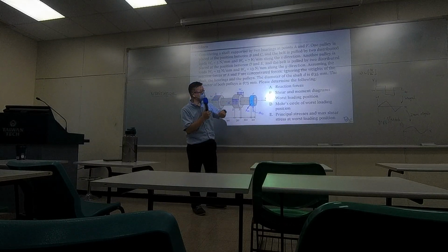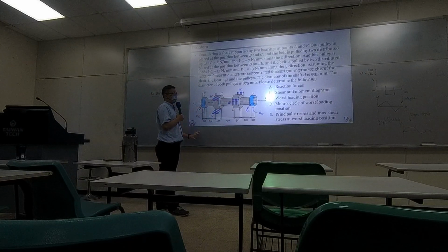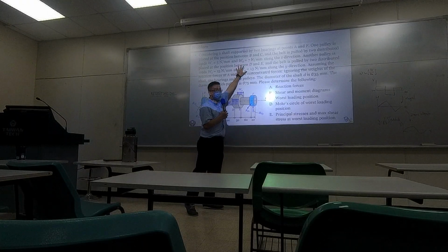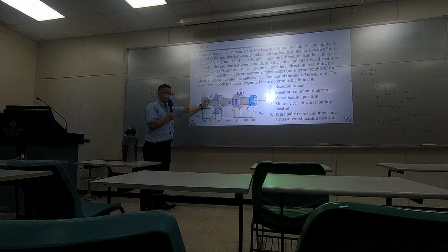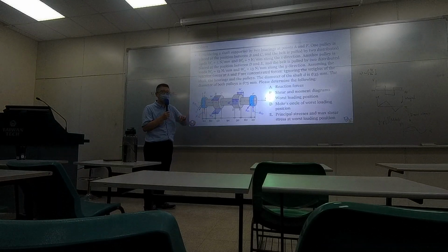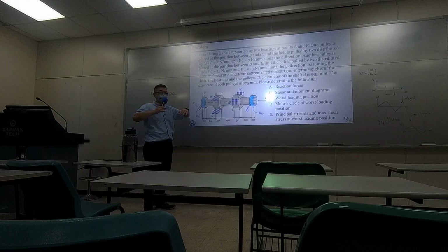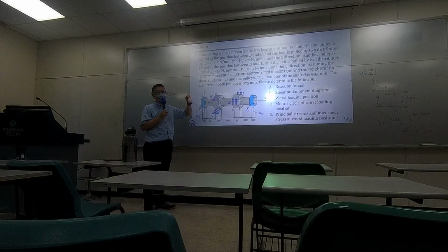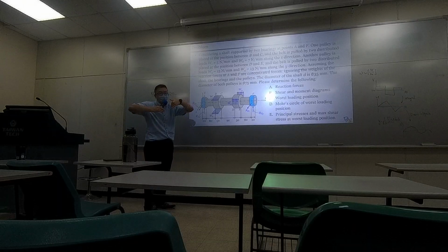Doing some kind of molding, right? So due to the torque generated here from the power of the motor, there will be another torque driving another system. So we know there will be some torque inside the shaft, and there are some weights for every component. So the shaft bends a little. If we design the shaft too thin, it's going to be weak, so when you put everything on top, it bends too much.